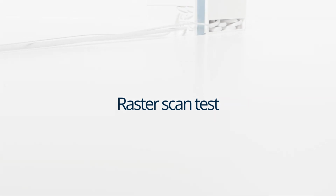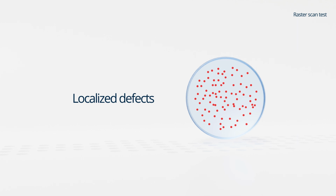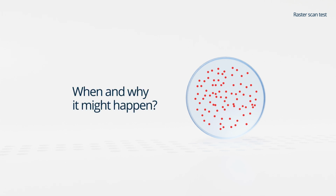There are several possible methods, and the raster scan test is one of them. The raster scan testing of laser-induced damage threshold is intended for cases when optics performance is limited by localized defects. It was designed specifically to deal with large aperture optics. Let's see when and why it might happen.